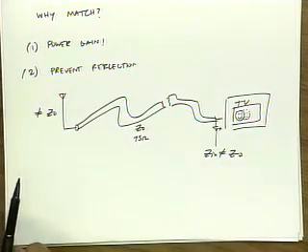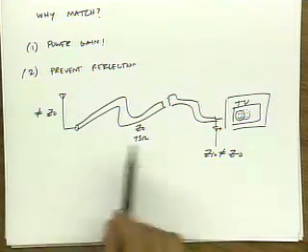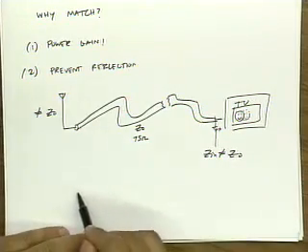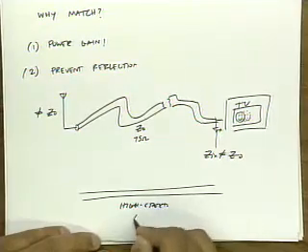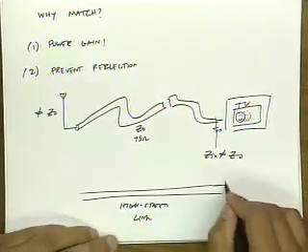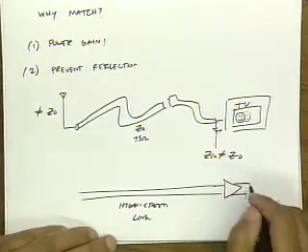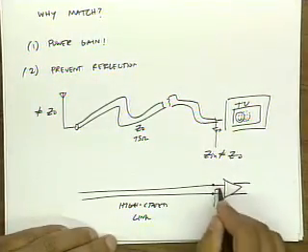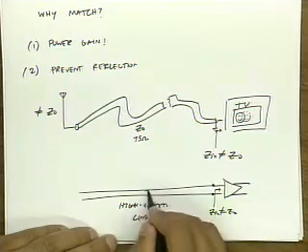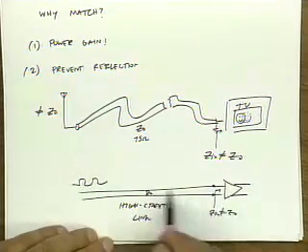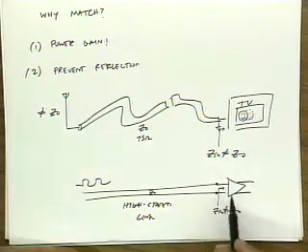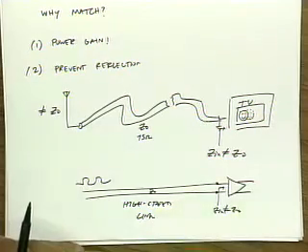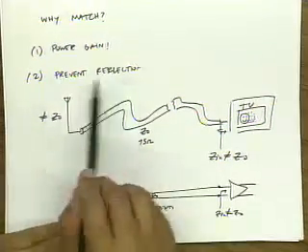Another example is a data communication system. If I'm sending high-speed bits over a high-speed link, and I have an amplifier at the end of the link, and the input impedance is not equal to Z0, then this data gets reflected and produces inter-symbol interference. So it gets harder and harder to correctly detect these bits. There are many situations where we terminate to prevent reflections.